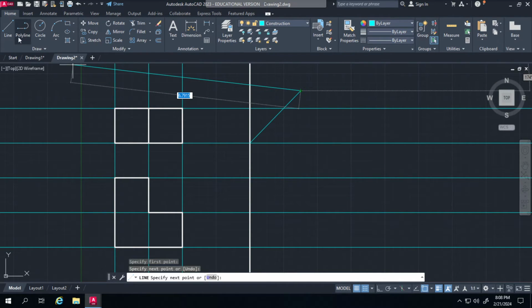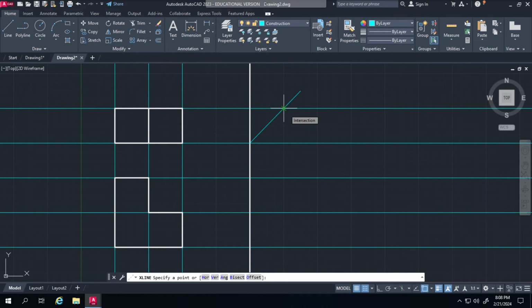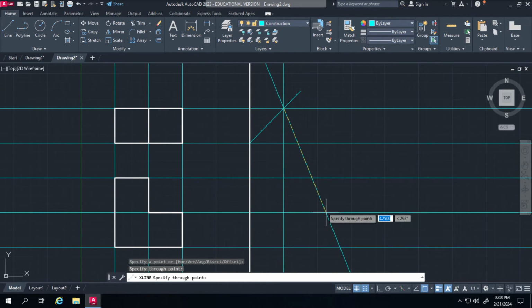And then I can go back to construction line, make sure we're in construction, and then right there where that line intersects, that represents this back half of the front view. So that's that back half right here, this line. If I find the intersection of that line and the miter line, and create a construction line that goes straight down, it represents the thickness of the part.